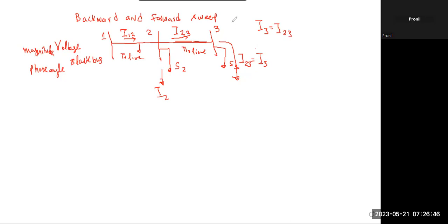So in forward and backward sweep, for the current calculations we do the backward sweep. For the voltage calculations, we go for the forward sweep. So the first steps, I'll write some steps.